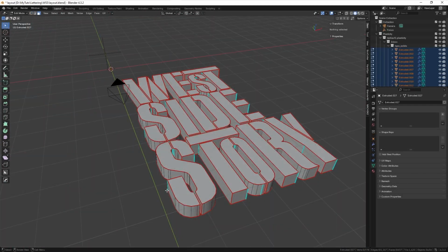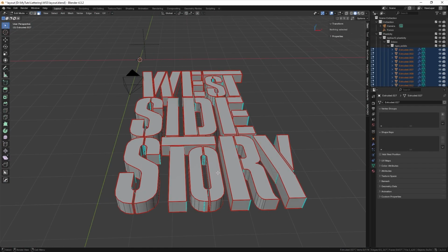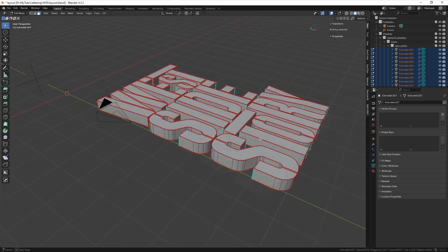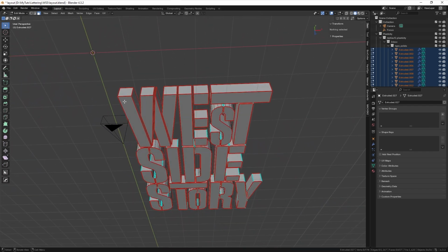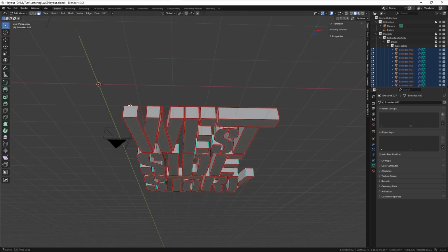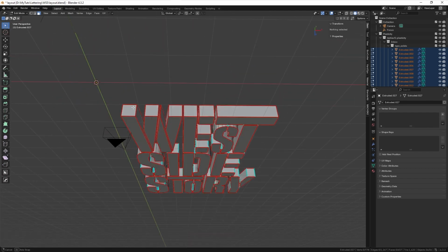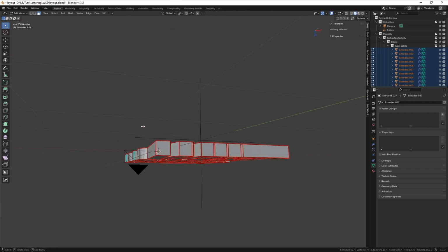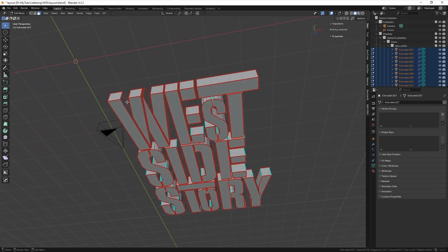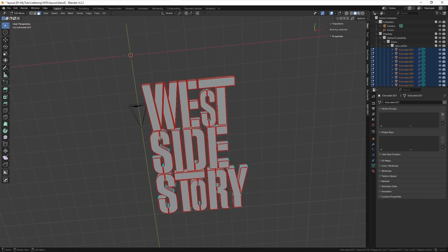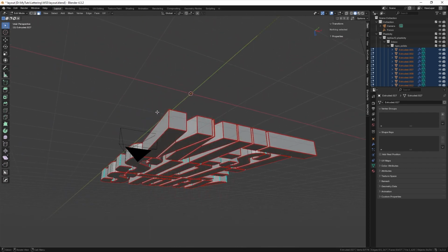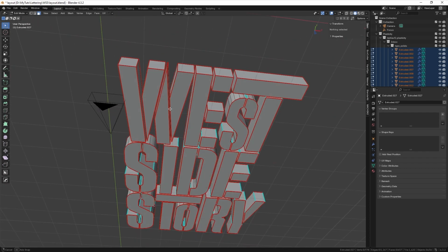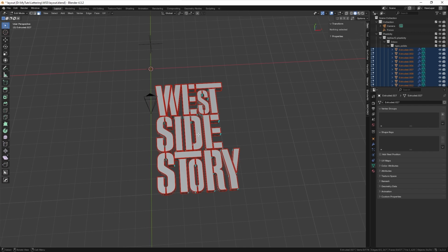Okay, if you have deleted the redundant seams, we can start preparing our model for the subdivision modifier. And by the way, you don't need to be that nitpicky when it comes to deleting redundant seams, because it's not the end of the world if there are too many seams or seams which are quite visible, like here in this case, because the material we are about to apply is quite forgiving. Even visible seams like here won't be that visible, so you don't have to be that accurate.